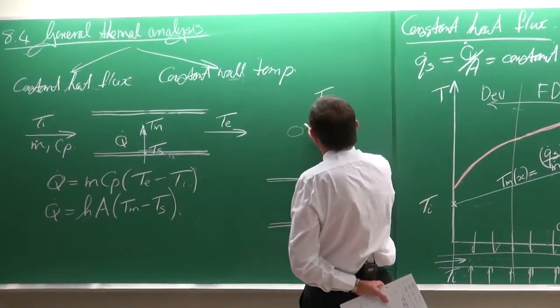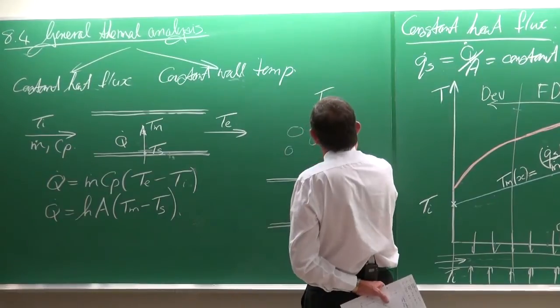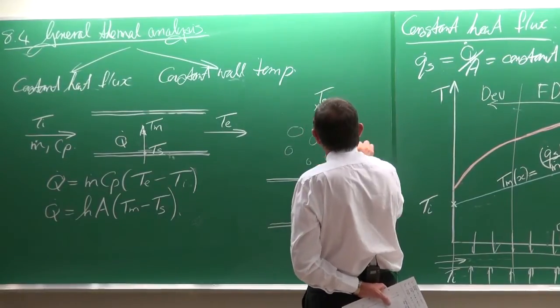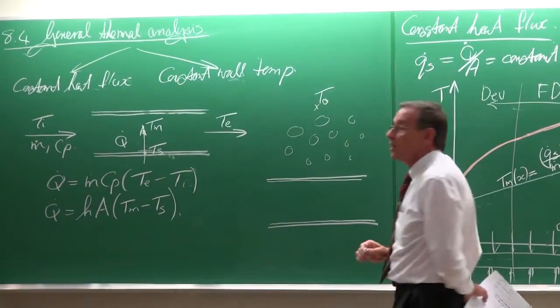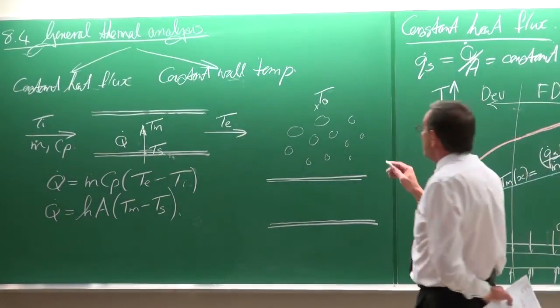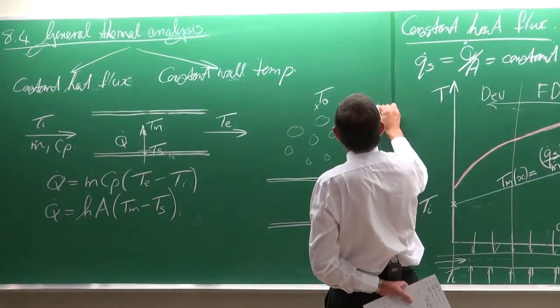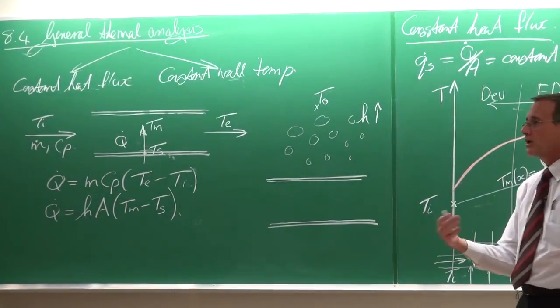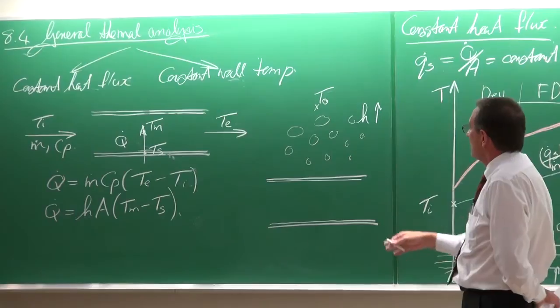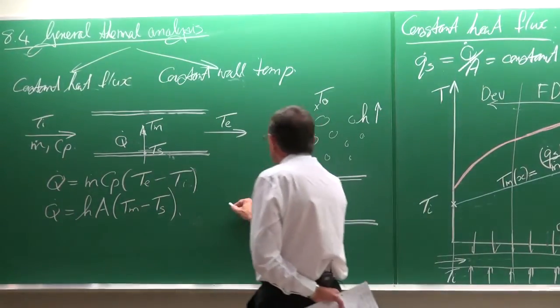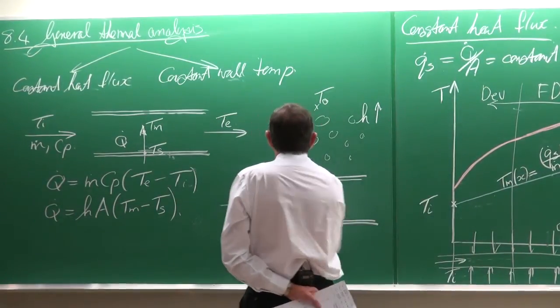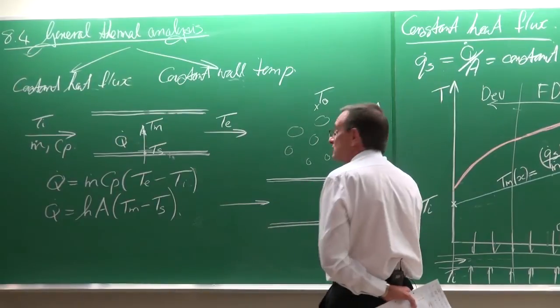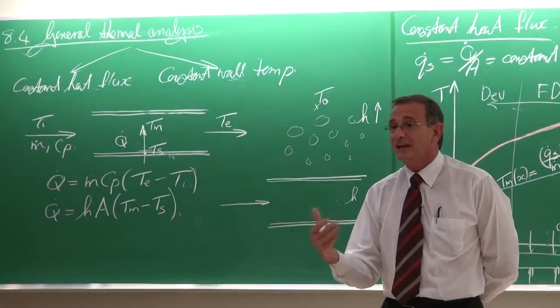If you have here two-phase flow, so we are talking of boiling, condensation, film boiling or whatever, then the heat transfer coefficients are extremely high, typically in the order of 20 to 30,000 watts per square meter. Okay. While here on the inside, normally you will have single-phase flow. And with single-phase flow, the heat transfer coefficients are on the order of about 100.